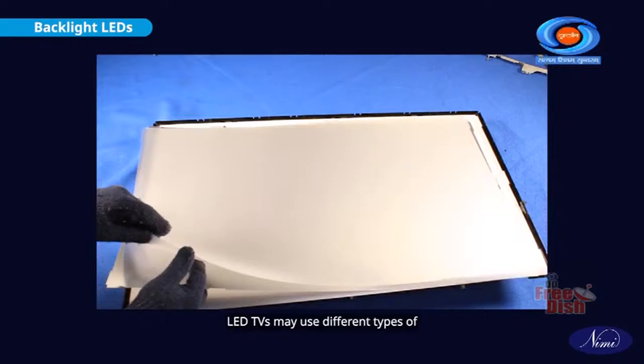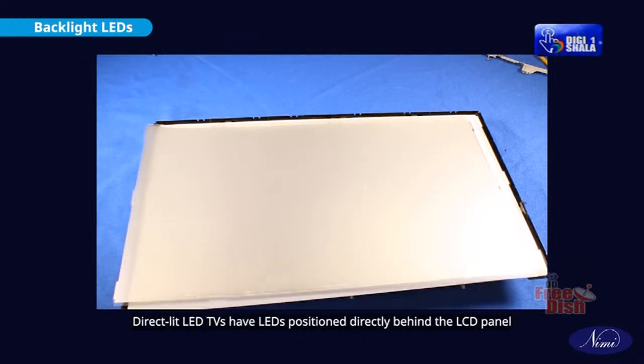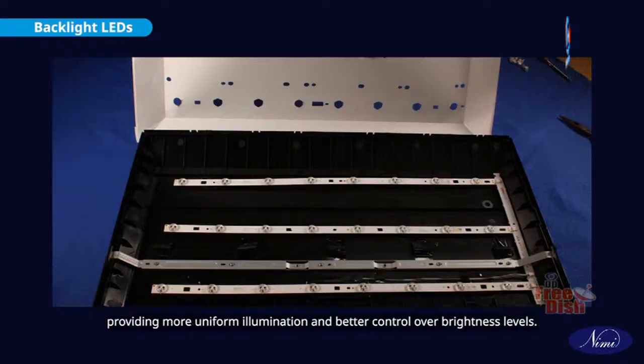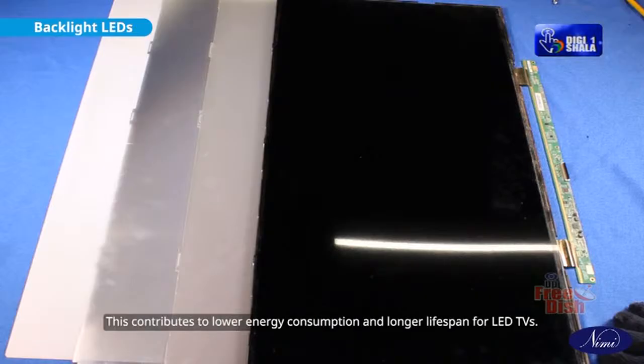LED TVs may use different types of backlighting configurations including edge lit LED and direct lit LED. Direct lit LED TVs have LEDs positioned directly behind the LCD panel, providing more uniform illumination and better control over brightness levels. LED backlighting is more energy efficient compared to CCFL backlighting as LEDs consume less power and produce less heat. This contributes to lower energy consumption and longer lifespan for LED TVs.